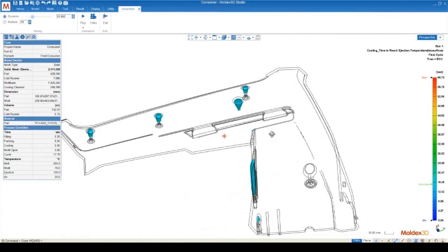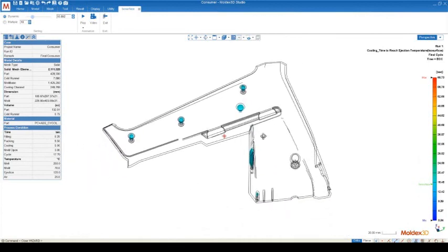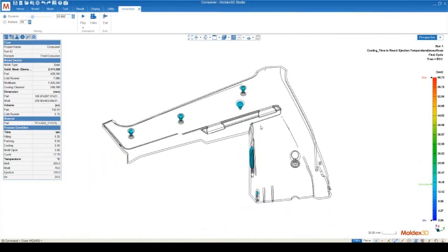So the filling time can be optimized through that simple equation. You can use that to give you an input, and then you can look at the temperature to see whether you've balanced the shear heating versus the cooling effect through the center of the part. Then you can use the molten core result in the packing and also the part weight curve to figure out what your ideal packing time should be. And you can use this time to reach ejection temperature to optimize your cooling time.